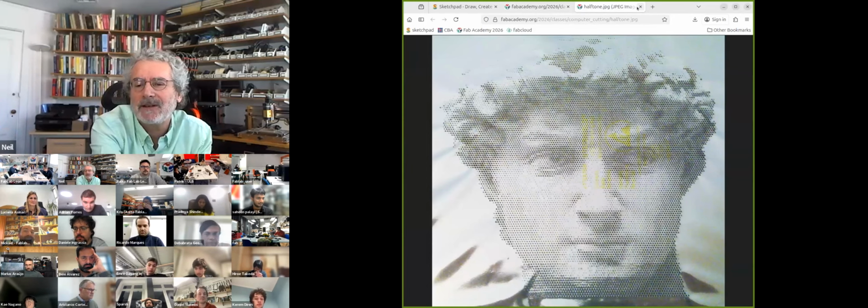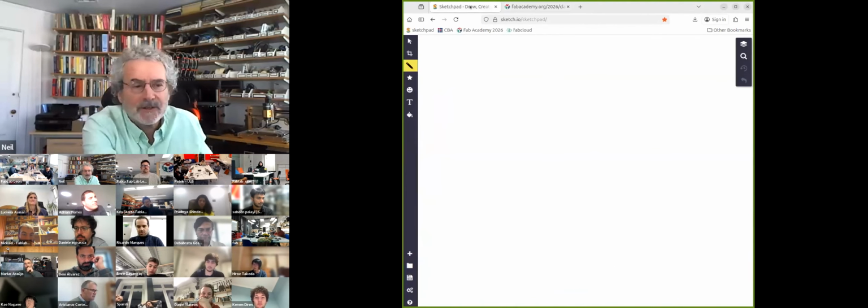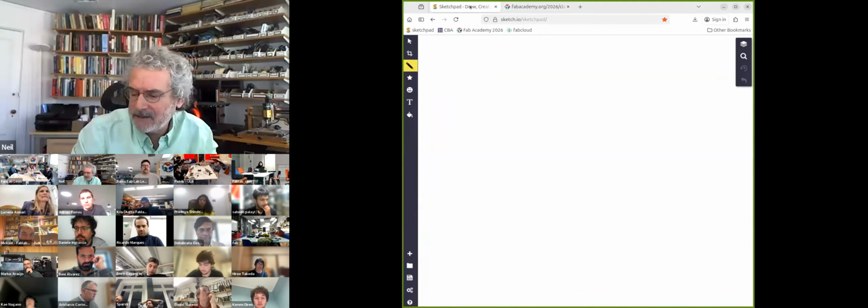Now, for this week's assignment, what I want you to do is design a construction kit, and you need to account for the laser cutter kerf. And so the key point is when you make a joint with the laser, and I'll talk about the joints in a second, this dimension needs to be within about 0.001 is the tolerance for that.